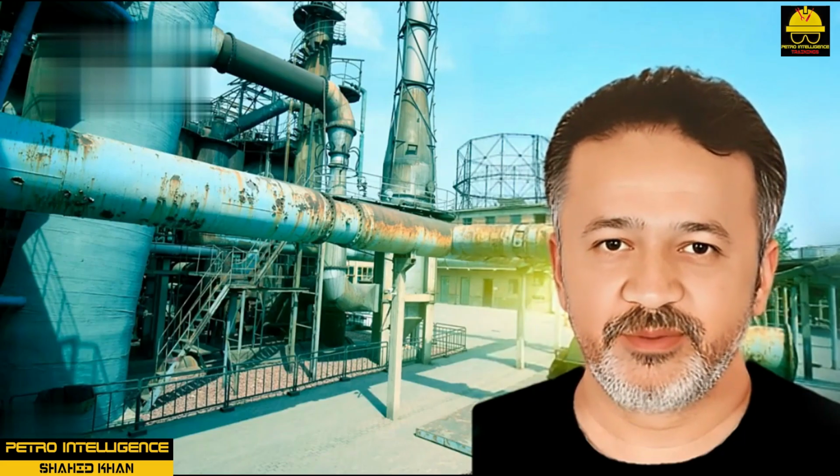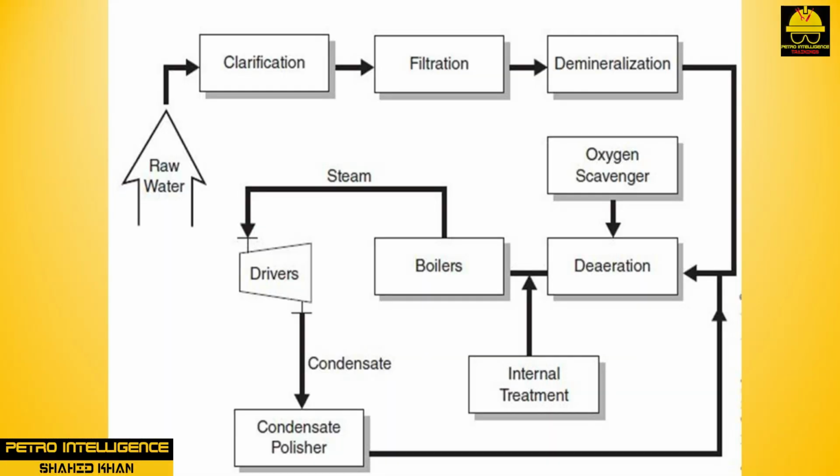Boiler feed water treatment. Boiler feed water treatment is the process by which suspended and dissolved solids are removed from the water used in a plant. Clean condensate and demineralized makeup water are deaerated in order to supply boiler feed water, BFW, to multiple BFW pumps.